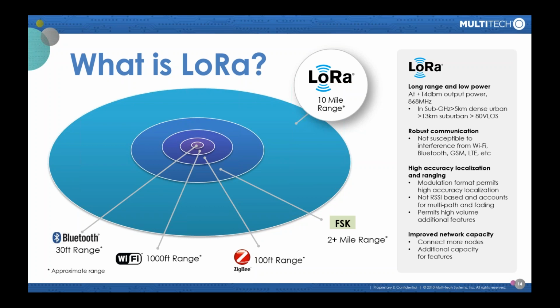So on the unlicensed side, we've got this thing called LoRa technology. LoRa stands for long range, and that's what it does. It has great range for connecting to assets out in the field. You can see the comparison here on this slide. LoRa is a long-range spread spectrum technology that operates below the noise floor. Because of its spread spectrum and the fact that it has error correction, it can break down the packets that are sent across the technology, capture some of those packets, utilize the error correction, and package the whole thing intact for your application.